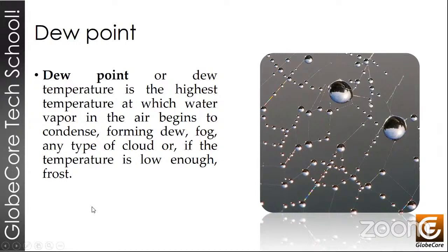The amount of water in paper is determined as a function of the relative humidity of the gas with which it contacts when it's exposed until there is a certain equilibrium condition between the respective moisture levels. At present, there is enough experience to safely say that this method for determining moisture content is correct and possesses sufficient accuracy.